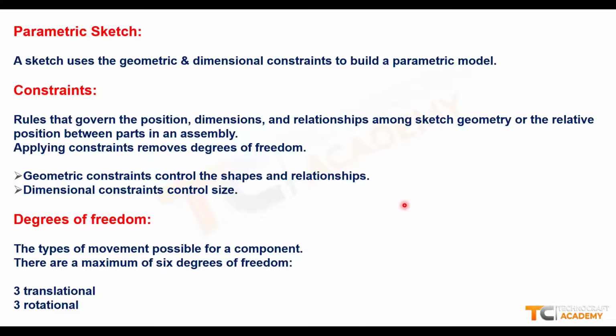No. So now assume you have applied the dimensions for that. Assume we have 20 and 30 mm sidewise. Now is it fully defined? Dimensionally, yes. But my question is whether it is fully defined with respect to both geometrical constraints and dimensional constraints. You have the XY plane, and in it a rectangle of 30 by 20 mm. Is it fully defined?